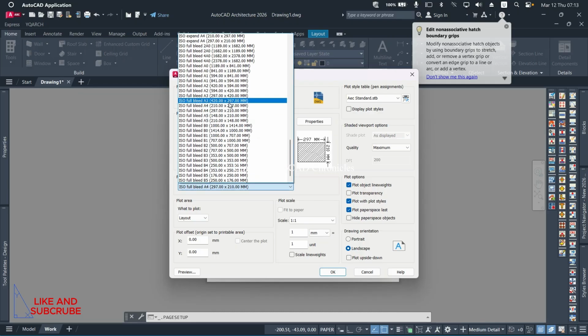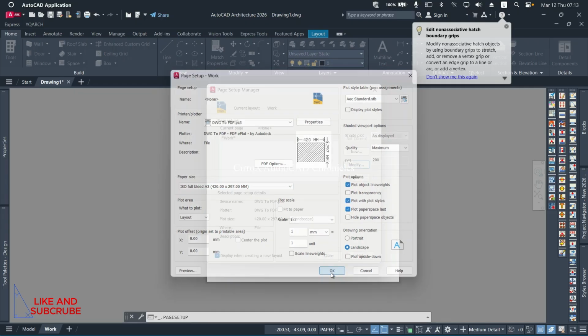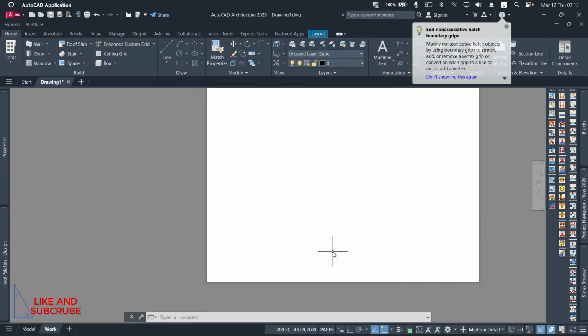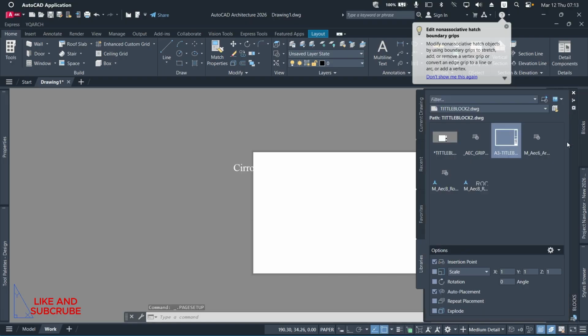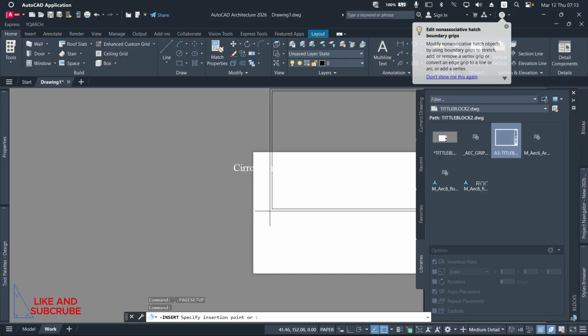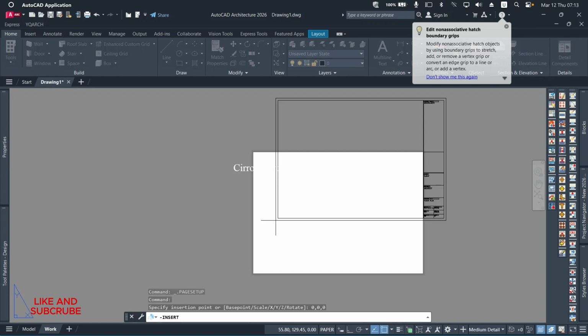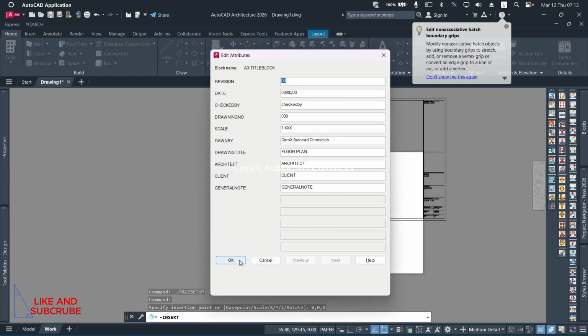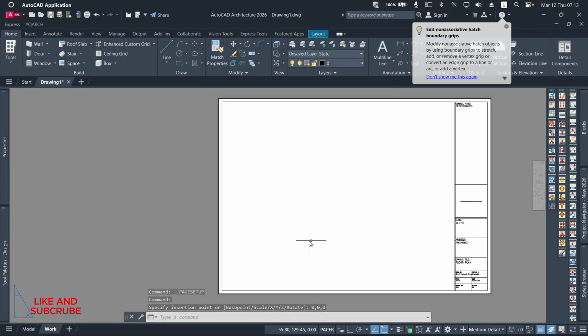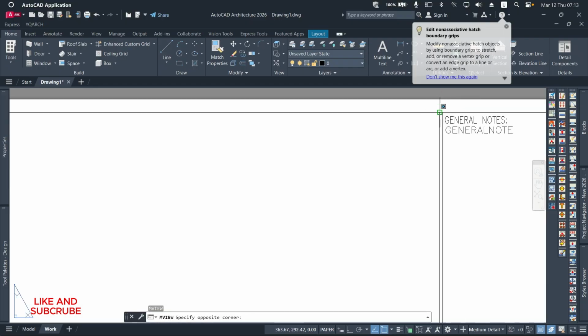So I think we'll be 83. That's what we want. So now I can bring in my title block, which is going to be 0,0,0 for this. I'm going to bring back the view, which is manage viewpoints or MV.